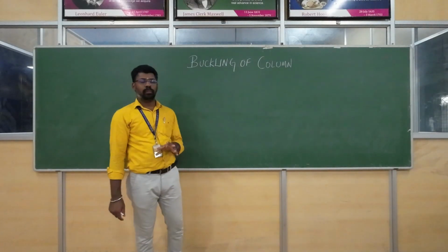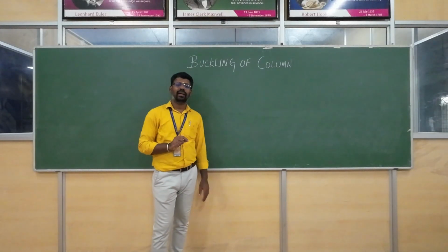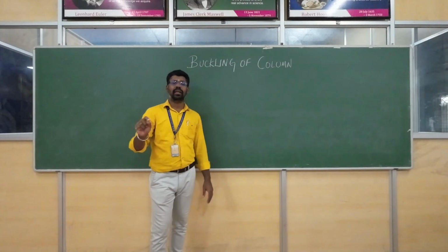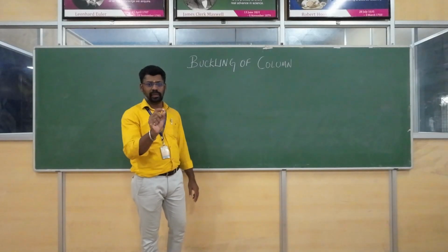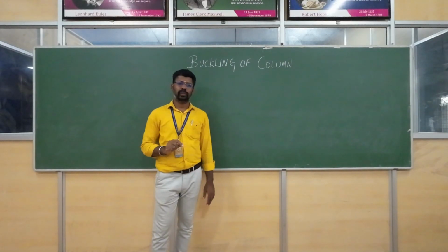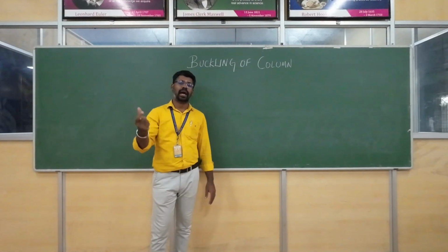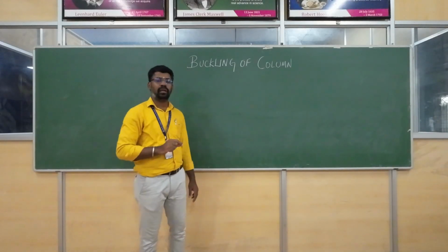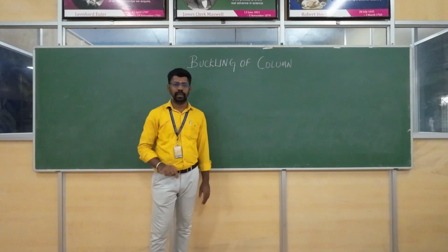Buckling of column is a structural engineering phenomenon that occurs when a column suddenly deflects laterally due to loss of stability. So there is a term called buckling load or critical load. This is the load where the column cannot handle any more load and will become unstable. In this experiment we are going to compute the critical buckling load both theoretically and experimentally.